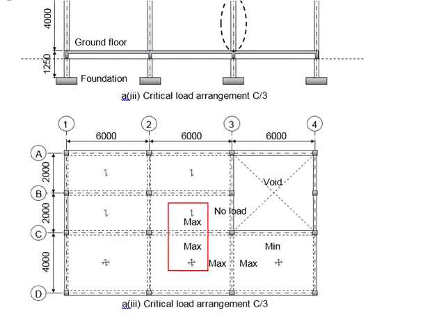Having the maximum load on this side, to get the largest possible moment in these directions, you will need to minimize the loads acting onto the beam here. No loads from the void, but there will be loads distributed here. Now you're going to make it the minimum loads for this slab. This shall give you the largest possible moment in these directions.